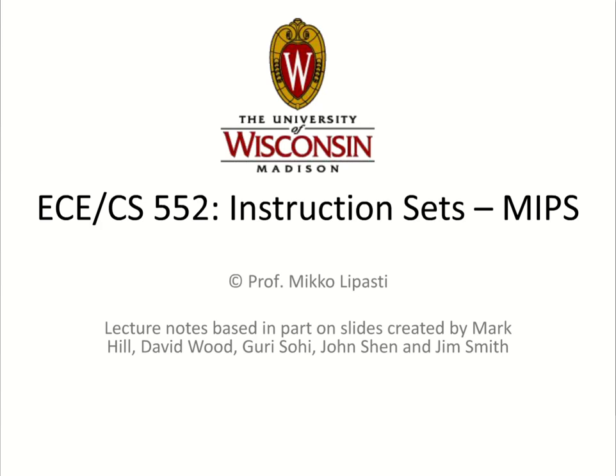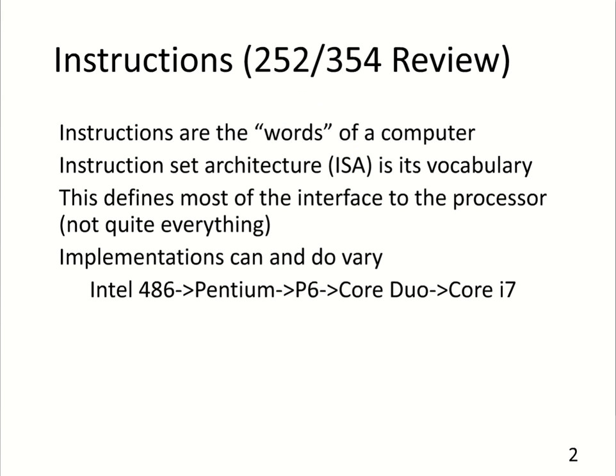To ECE CS 552, lecture on instruction sets with a focus on MIPS. The focus of this lecture will be on instruction set design. This is really going to be, in part, a review of 252 and 354. Instructions are the words of a computer. In other words, the instruction set architecture makes up the vocabulary that the processor is able to understand and serves to define the interface to the processor. Most of the interface. There are other things that also need to be defined that we'll touch on later.